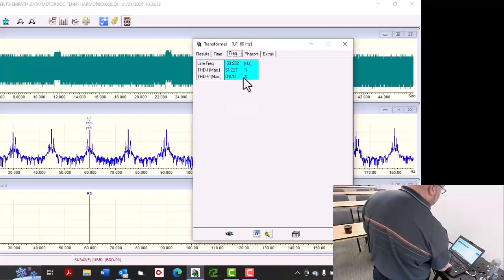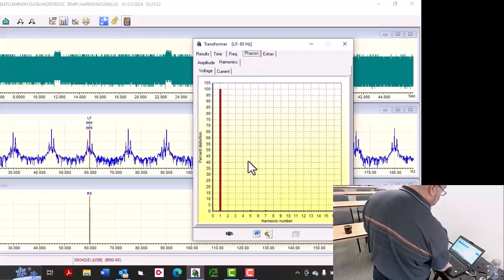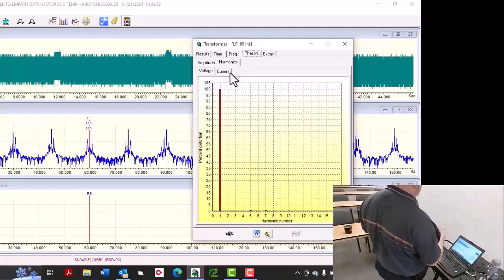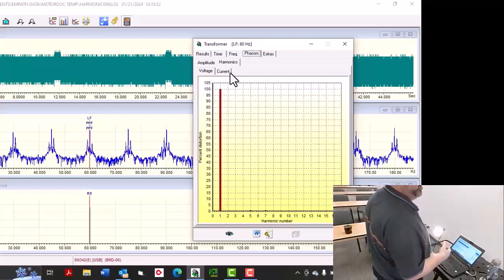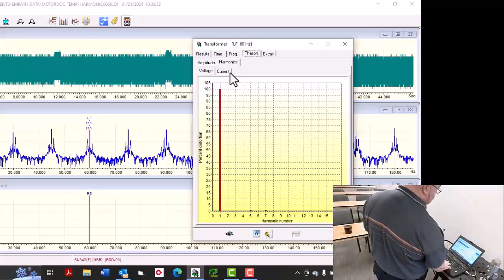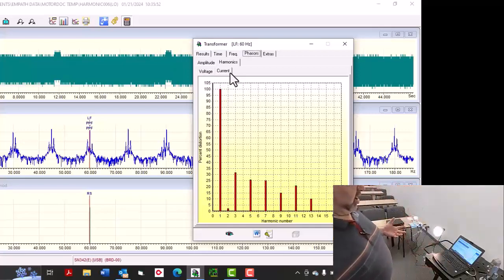We got 61% total harmonic distortion. The phasors, here's voltage, still pretty nice. So it does a good job of maintaining voltage plus big load behind it. In this exact circuit, I don't have a lot. I unplugged everything in the classroom for this. But there's our harmonic distortion again in current, which is relatively large, and it's not just a triplen harmonic.